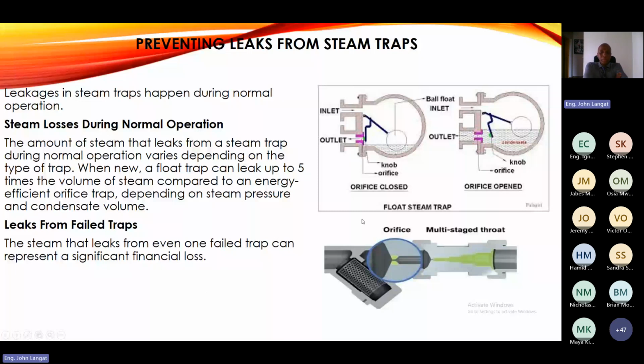On your right here, I just wanted to mention that these are two types of steam trap. These are the float steam trap, and we have an orifice multi-stage steam trap. The first one, the float steam trap, normally requires a lot of maintenance. While the orifice is new in the market, I think it's now around 5 or 6 years, but there's a lot of resistance to its adoption. But it's quite effective also, especially when it comes to saving on steam losses. What I need to tell you is that the float steam trap does not permanently prevent steam losses downstream in the condensate line. There's some steam that passes, however, in small quantities. Of course, I hope Spirax Sarco will not come after my neck.